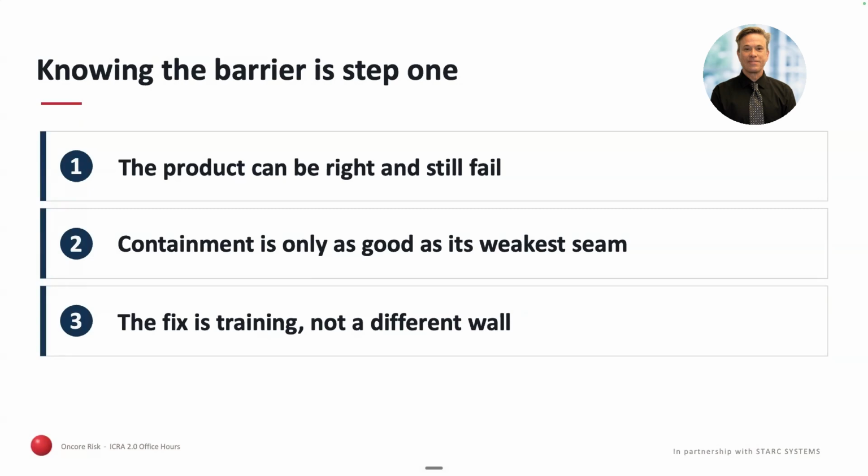When we actually developed the ICRA form for ICRA 2.0, one thing that was asked by the regulatory agencies is, please explain to people how to put up barriers safely in an occupied space as to not create dust and debris and other things that might harm patients, and how a wall should look and how should it be inspected on a daily basis and make sure that it's staying in place.